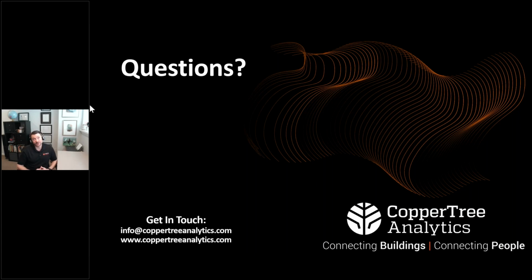I guess I'll ask first, is your BAS Delta? Yep, it's Delta. So what we've done now with Delta is there's the IntelliVault product, which is a server-based archiver. We've created an integration for the IntelliVault product, both IntelliVault and IntelliCloud, which is a cloud-hosted version of it, where we pull the trend. Just like the Copper Cube used to push the data directly to Kaizen, we pull the data out of the API on IntelliWeb's IntelliVault, and we then push it up to Kaizen. In that case, we do still require a K-Link sitting in parallel with the IntelliVault.